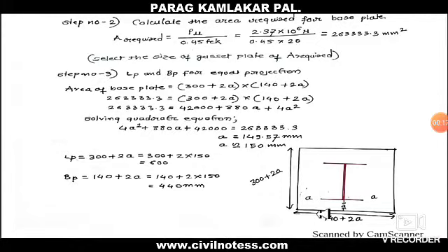So here you can see the diagrammatical representation of the base plate. Here it is the ISMB section. I have not even shown the sketch of the pedestal. This is a top view. This is the base plate, okay. The ISMB section is situated in the center of the base plate. So the distance from this point to this point, and this point to this point, is A, okay.